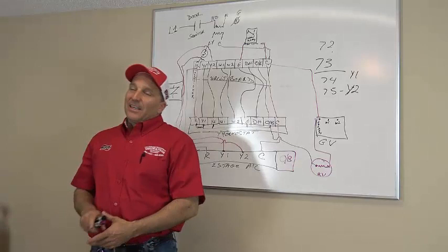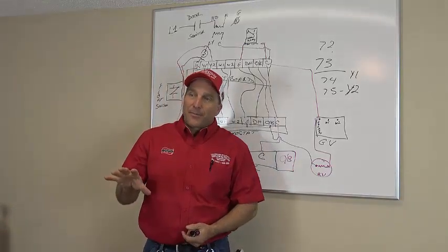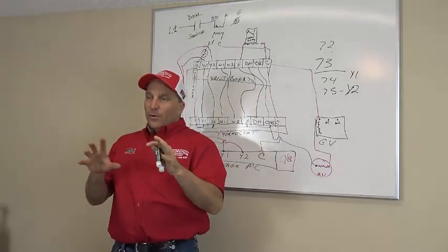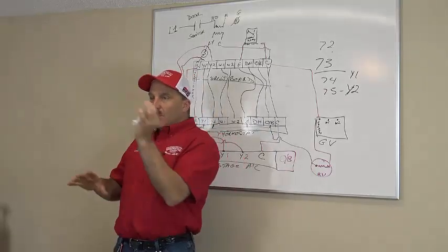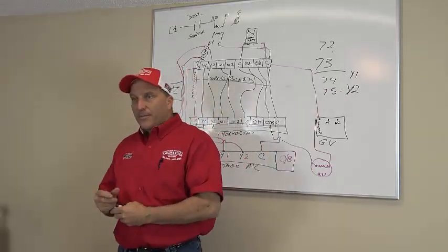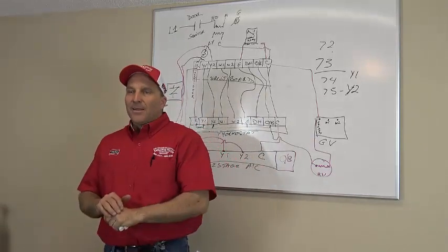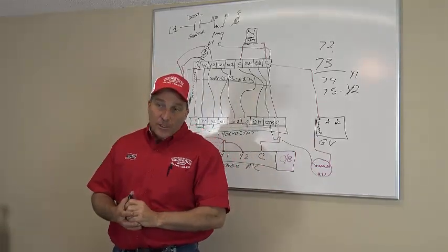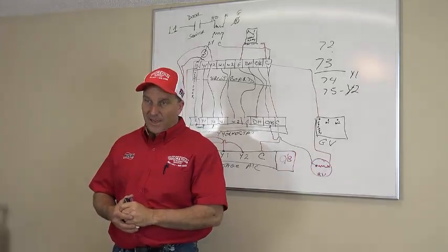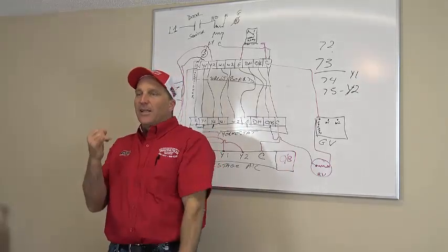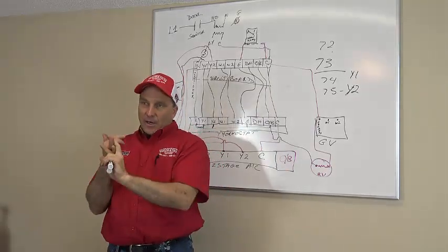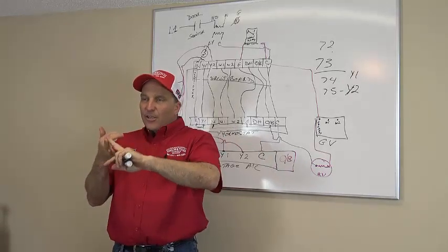Because if I have a digital thermostat, programmable digital thermostat, Honeywell 8000 Wi-Fi thermostat, let's just say. It's got all these terminals on it, right? Now I have to go into the configuration mode and I have to tell that thermostat, I want you to be a single-stage thermostat, a two-stage thermostat, two-stage heat, two-stage cool.